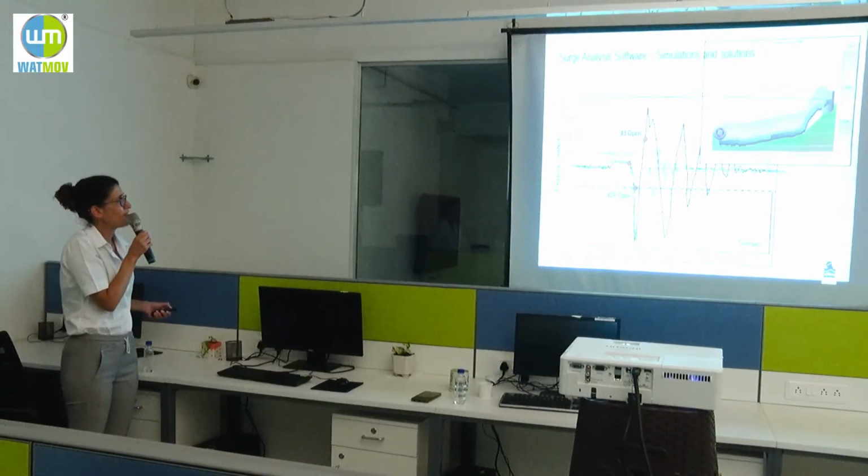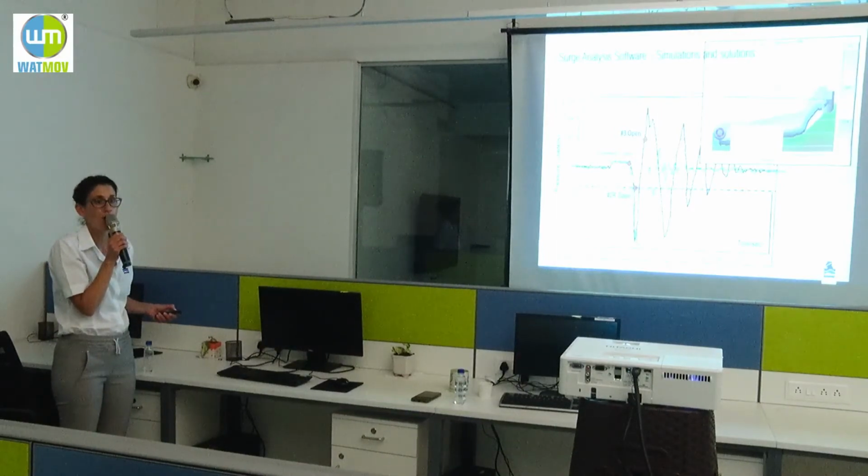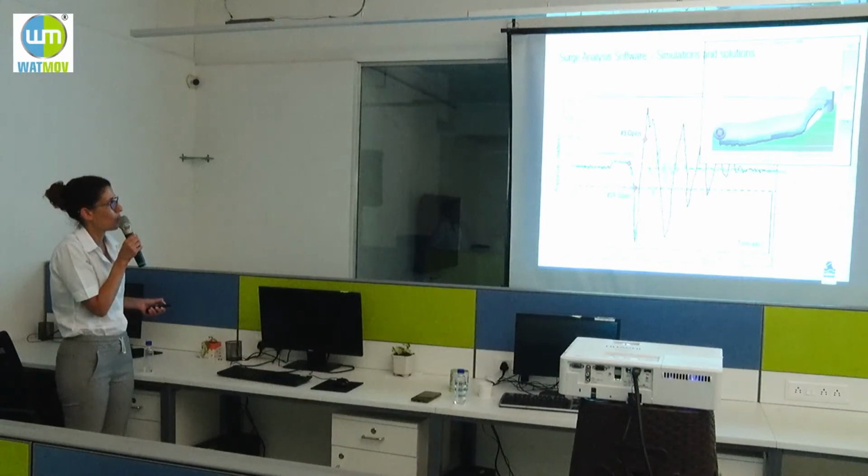And the valve is already waiting open and starts to dissipate the water. You can see that the oscillations are much more moderate and very fast. We are stabilized on the static pressure, back to the static pressure. Between the setting of the high pressure pilot and the low pressure pilot, between the red and the blue lines